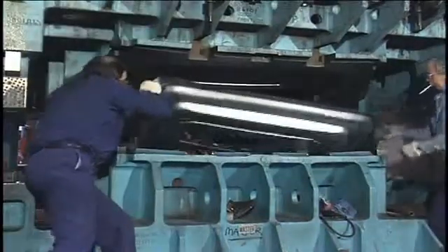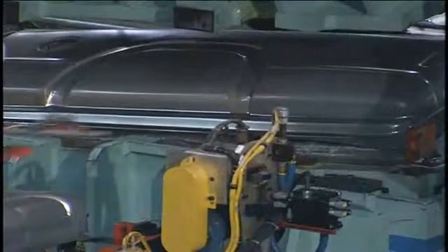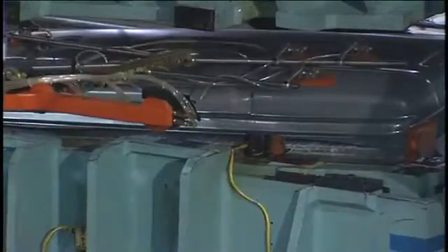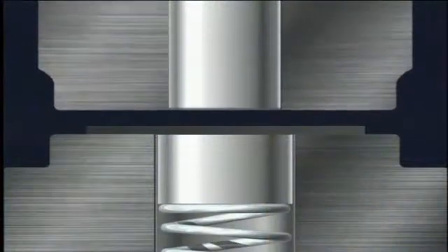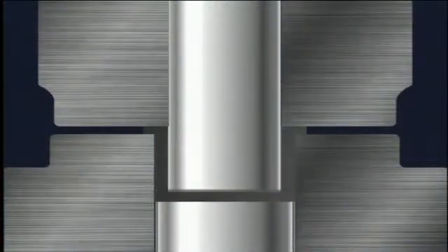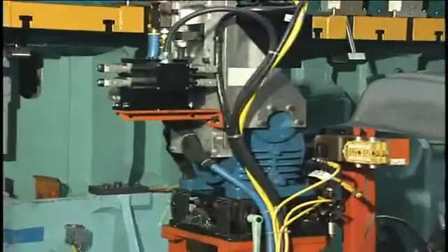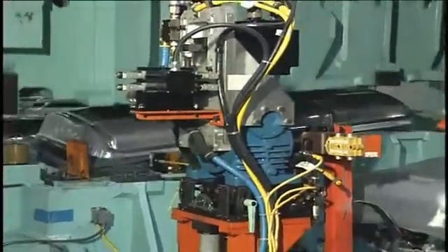Various complex forms may be produced by drawing. Drawn parts may vary in size from small parts up to aircraft and automotive parts large enough to require mechanical handling equipment. For properly draw-formed parts, the force exerted by the punch must be great enough to draw the metal over the edge of the die opening and into the die. Additionally, the drawn metal must have a combination of strength and ductility to avoid rupture in the critical area where the metal conforms from the punch face to the punch sides.